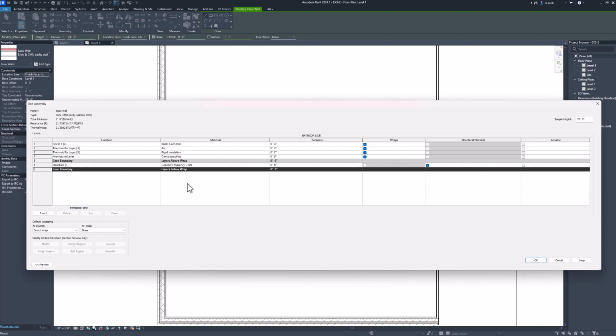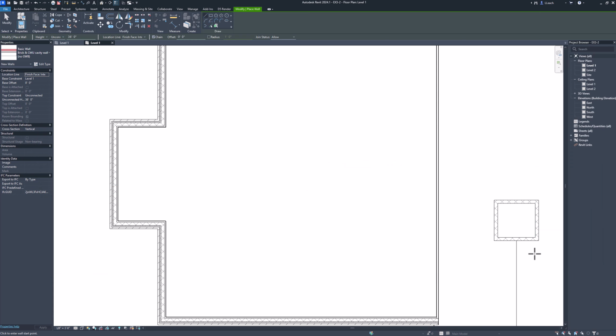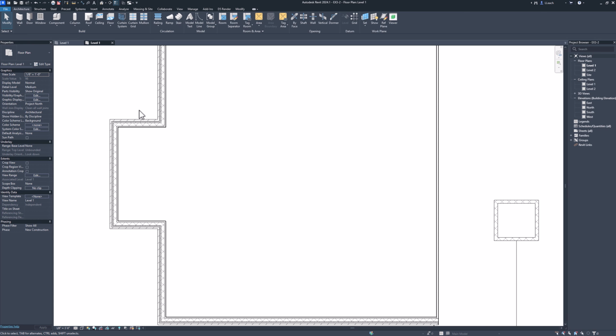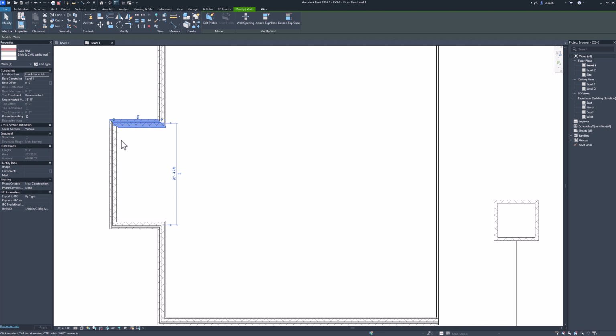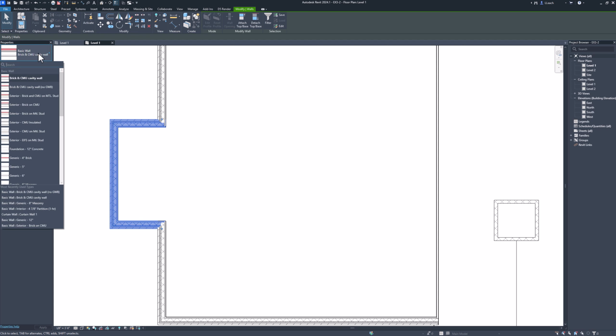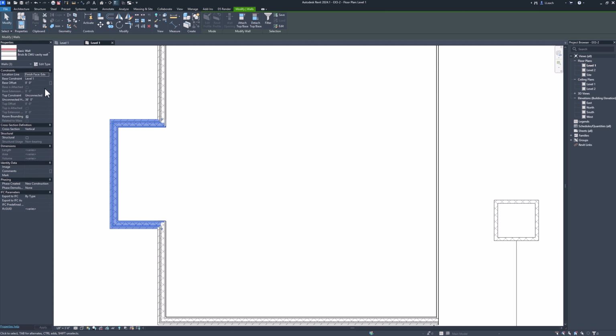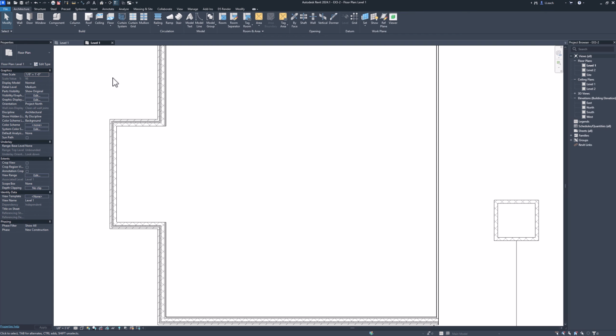Okay, so then we're good with that. So I'm gonna hit okay. Hit okay again. So now what we're gonna do is these 3 walls here, let me cancel the modify, cancel out of that. So these 3 walls we're gonna change to the wall that we just made. So I'm gonna select, left click, hold the control button and select these other 2 walls. And now go up to this, properties. So we're gonna change that to the cavity wall no gypsum wallboard that we just created. You can kind of see it remove those. Hit the modify to cancel out of this.